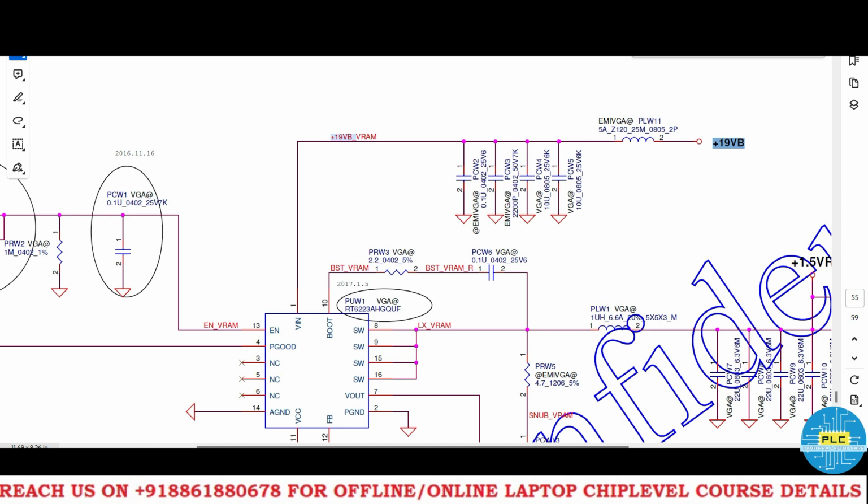So this IC may be the faulty, or this section, these capacitors may be the faulty in case you get the short in number one side. In case after removing this, in case of two side there is no short, then on this side only the suspect components are these capacitors and this IC. In case after removing this there is no short, here is the short, again you need to check further.